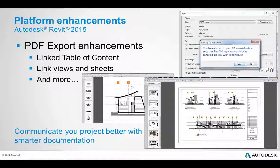What we're finding now is that the links that we have inside of Revit for section callouts, plan enlargement callouts, and so on, are now becoming hyperlinks in our PDFs. And this can help whoever we're sharing the PDF file with, in that they can now click on those hyperlinks and it'll actually browse to that page. I tested it once: if I did single sheet exports of my entire set, it would open and show, per the hyperlink, the other PDF file, but it doesn't function quite as efficiently as if I were to do an entire PDF set. It just depends, of course, on what our project may need and exactly how we might work with that. So that's a big enhancement that I'm really liking.